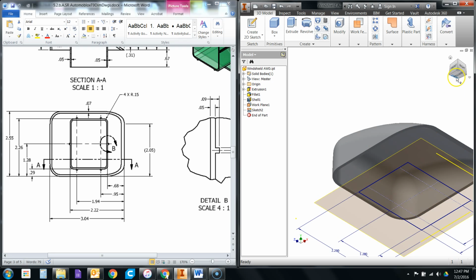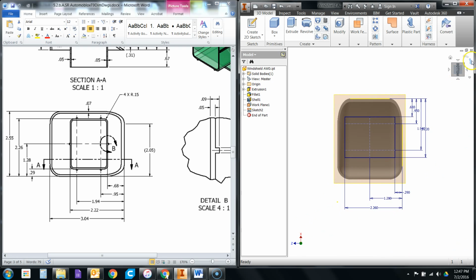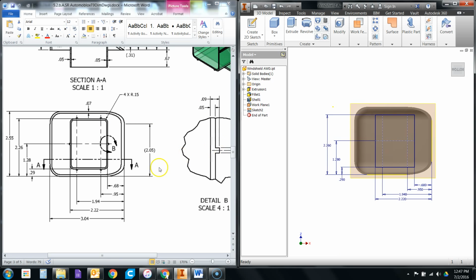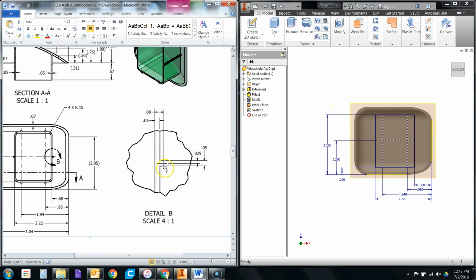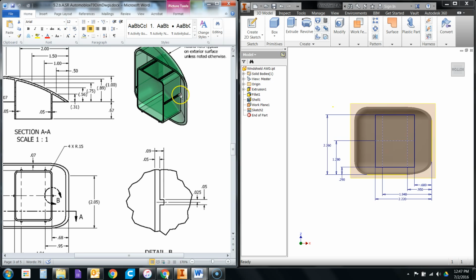Now, the trick is that you probably really want to play with this a little bit. You'll notice that on the detail sketch, there are little, let's call them rails or knobs, that stick out from this feature. They're features in themselves. They're these little pieces here that rub up against the inside opening of that passenger base, or that passenger section that's made out of wood that we made in the previous video. And you'll find that they're what grab the wood. They're what touch it for friction and hold it in place. We don't want those to be shelled. We want the rest of the object to be shelled.